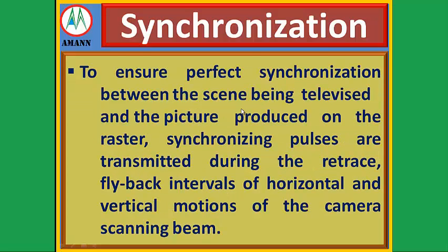To ensure perfect synchronization between the scene being televised and the picture produced on the raster, synchronizing pulses are transmitted during the retrace, or flyback, intervals of horizontal and vertical motions of the camera scanning beam. Now, synchronization.